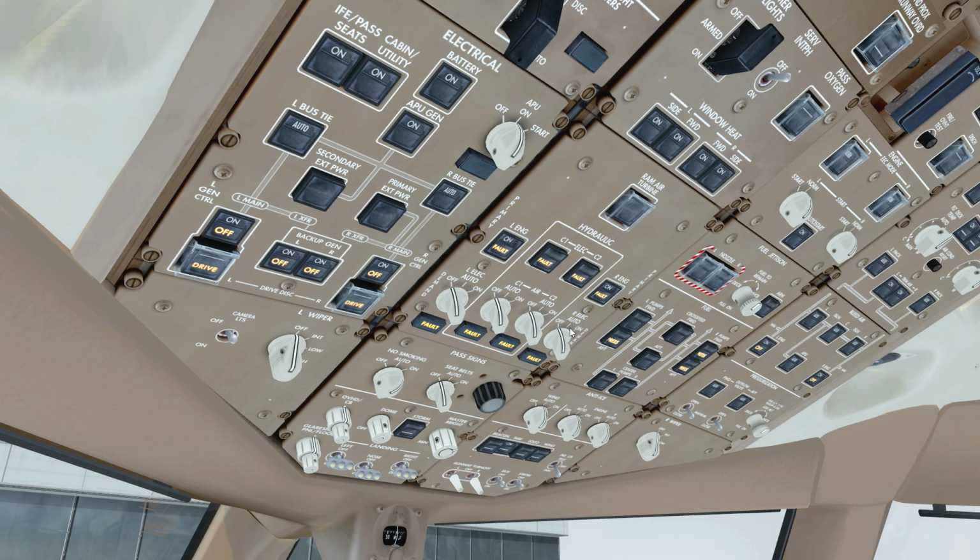So always put the right electric demand switch on auto first. Wait for the fault light to extinguish. There we go. And now we can put on the central primary hydraulic pumps and then the other demand switches. Okay, so it's a bit tricky, keep that in mind. So right now all the primary hydraulics are running.